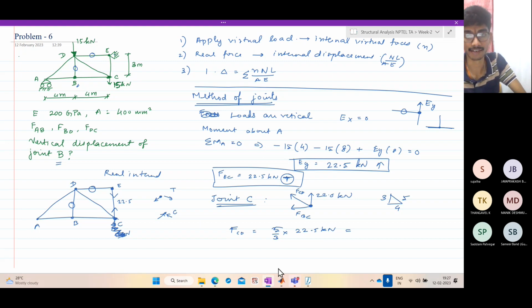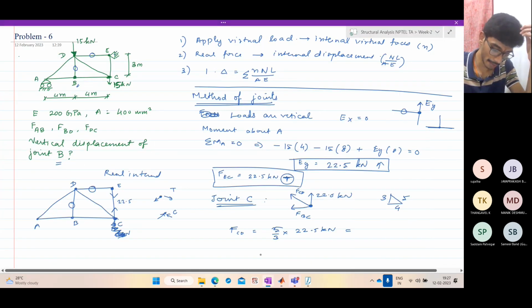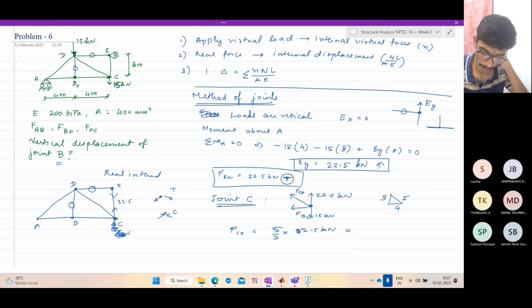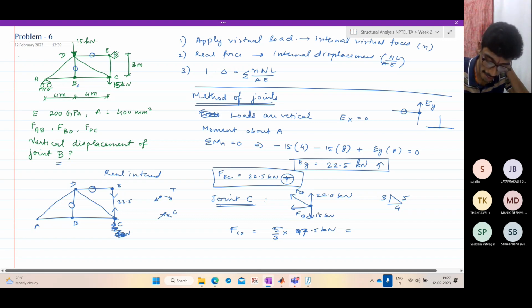How much is that? Let us do it quickly. So 5 into 22.5 by 3, 37.5. Oh, wait. You also have a 15 kilonewtons downwards. Yes, 15 downwards. One more force is there. Yeah, I missed it. Sorry. Now I'm noting it. So we get FCD: you have 15 kilonewtons downwards and 22.5 upwards. So the net force is minus 7.5, and FCD plus this equal to 0.